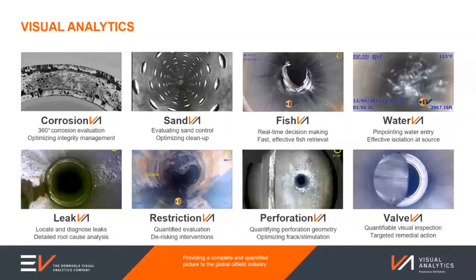In a lot of cases, a simple bridge plug can be the most effective. If you're absolutely certain that you don't have any hydrocarbons coming from the toe of the well below that water entry, then a plug, very reliable, very easy. You can verify its performance very simply with an inflow test, or even actually placing a camera on top of it and looking for bypassing if that's the case. Alternatively, as long as you treat them well, mechanical solutions such as straddles and patches, again, great track record of using them. They just come with that slight downside in some instances that you do lose access to the well below. But again, if that's something you're willing to work with, then fine.